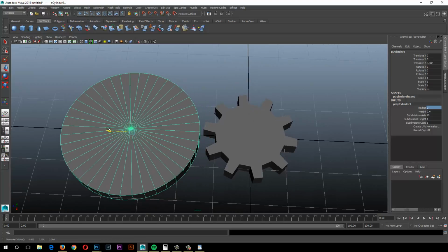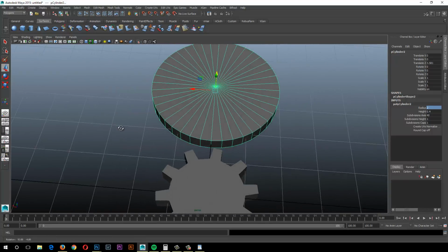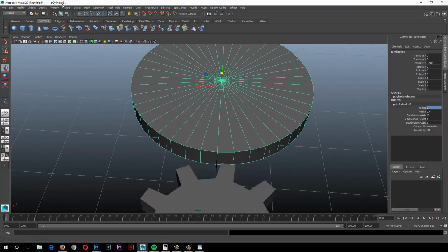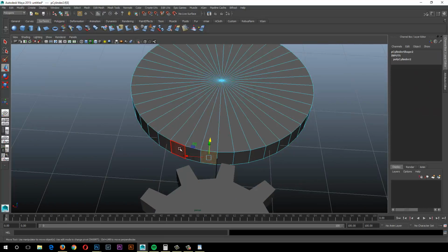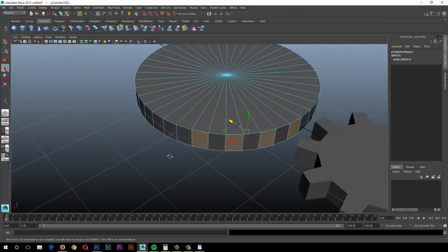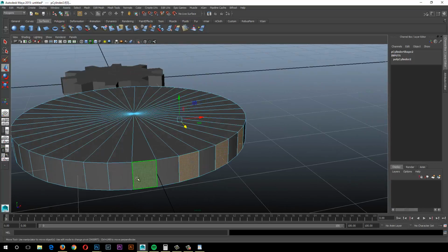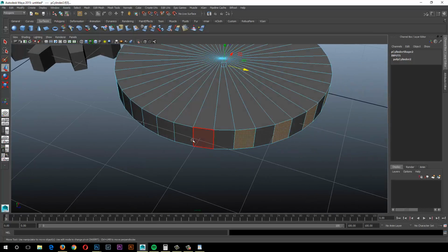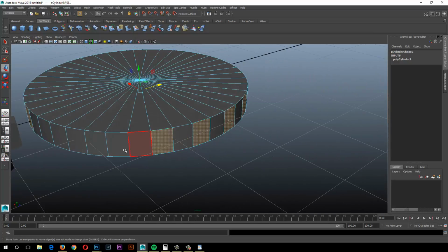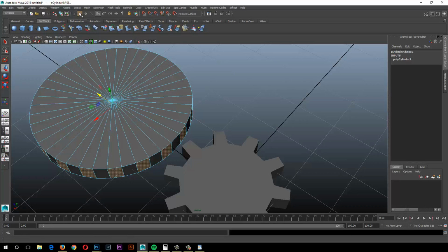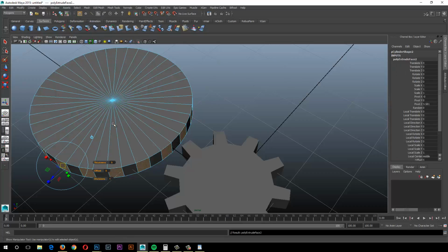So I'm going to move this off to the side and extrude out my teeth, and just to make my life easy, you can see, because this is double, this lines up pretty well. I am going to make sure I pick this face starting in here, which is already kind of pointing into that space, and that should put a little bit less guesswork into figuring out how to line these things up once they start rotating. I am just going to select every other face again and extrude these out the same way I did before, using the same values. So my teeth again are the same length and the same tapering. You could probably have those slightly different, but this is just going to make it work so much better, having everything be the same.